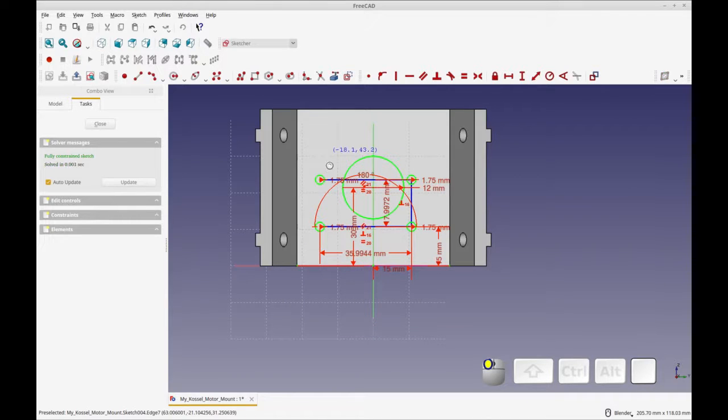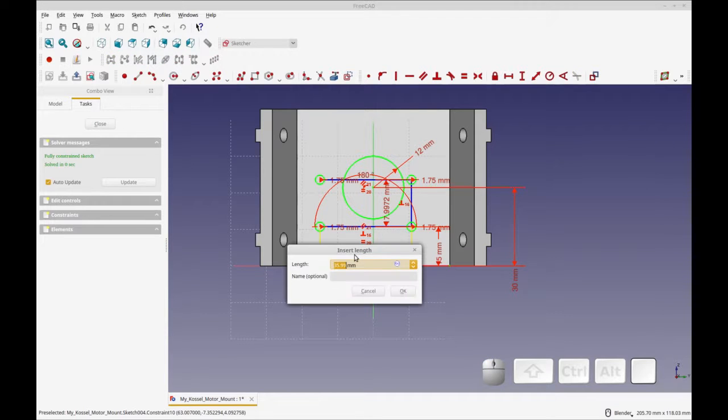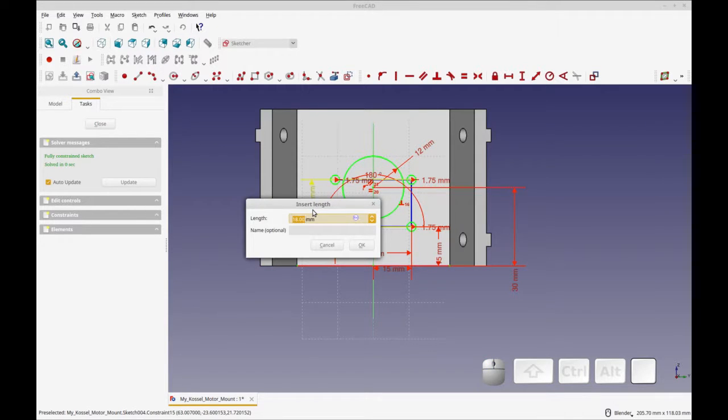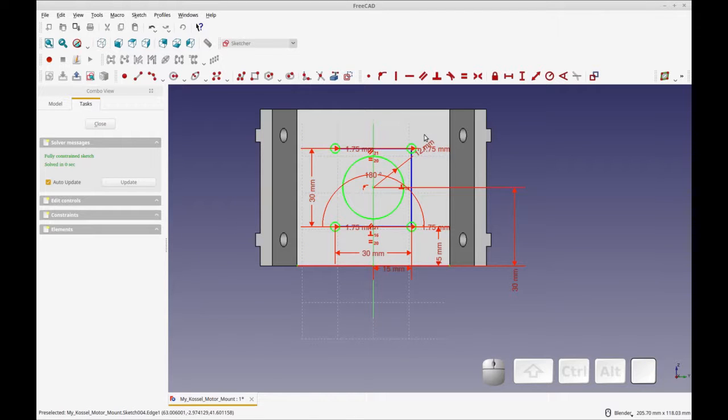and we're not going to slide it up, we're just going to set the radius, where is it? Oh, there it is. So this will be set to 30 millimeters. You can see the symmetry still. 30 millimeters, loving it. And then this one is also going to be 30 millimeters. Yep. Okay, and that's it. I think our sketch is fully constrained at this point, and we have all the elements we need for the motor cutout.